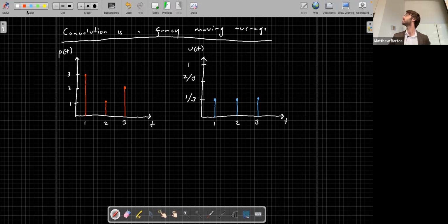Give me 5 more minutes, and I'm going to show you how we can use convolution. This is the same procedure you'll use on the homework, so I think it will behoove you to follow along here. From our formula for discrete convolution, the discharge at time index n is equal to the sum from m equals 1 to n of P_m U_(n minus m plus 1). Let's compute the Q at each time index using this formula.